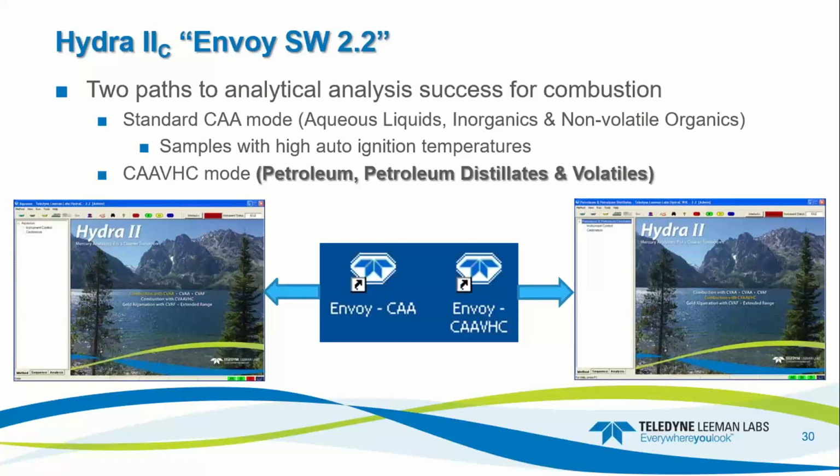It goes into the injection port, the system seals itself up, and then the radiant heat from the catalyst zone is going to gradually flow into the combustion zone, and by default, it's going to raise slightly and very slowly up to about 170 degrees C. During that process, the volatile sample is going to go through its auto ignition, and you may hear a faint pop from the explosion within that cell from it combusting.